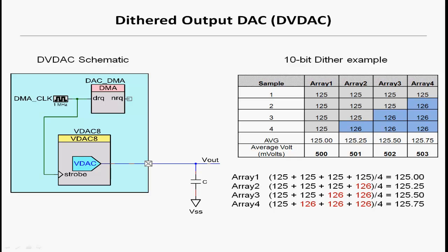By dithering the small amount, the modulation noise is much easier to filter out. Normally, this dithering would require a reasonable amount of CPU cycles, but instead, PSoC3 and 5 have DMA. This can all be done in the background with no CPU overhead, except when the desired output value is changed.